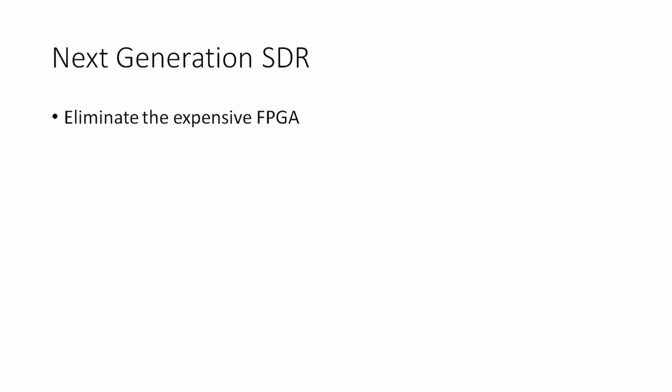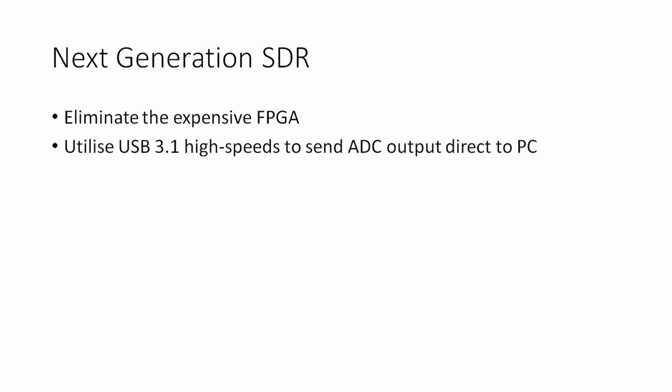So what about what comes next with SDR? Well, one of the things that's been proposed and has already started is to get rid of the FPGA, because the FPGA is very expensive on its own, but it also requires dedicated programming skills, because it's a completely different programming language to set it up. So the plan is to get rid of the FPGAs.